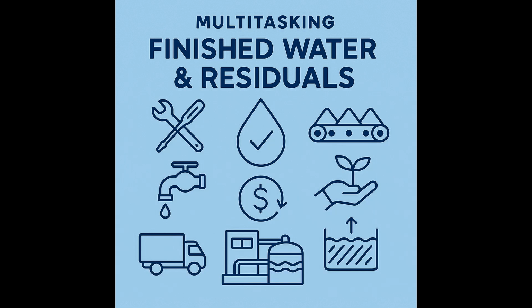Pros. Potential for beneficial reuse, particularly phosphorus binding. It can be a lower disposal cost compared to some landfill options, and it can contribute to a positive public image around sustainability if managed transparently and effectively. Cons. The regulatory landscape, especially PFAS, is complex and rapidly evolving. Major weather or seasonal access limitations can create storage and scheduling nightmares, and community perception is fragile. Negative headlines about PFAS, even if unrelated to WTRs, can create opposition.